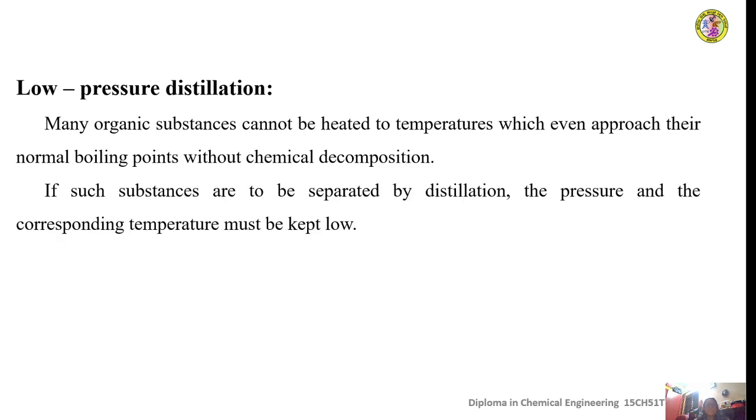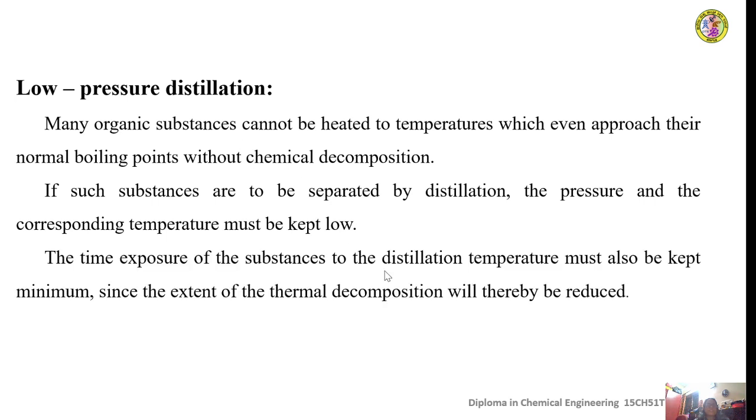So if such substances are separated by distillation, then you have to see that the distillation is carried out at a very low pressure, thereby you can keep the vaporization temperature at a very low level. If you carry out the distillation in that way at a very low pressure, then you can see that these substances can be separated in pure form without any thermal degradation of their structure. So that is where the distillation carried out at low pressure plays an important role in the separation of these important organic materials.